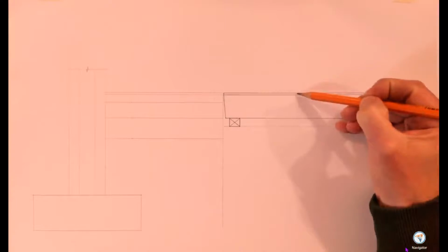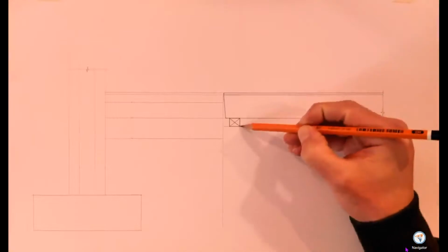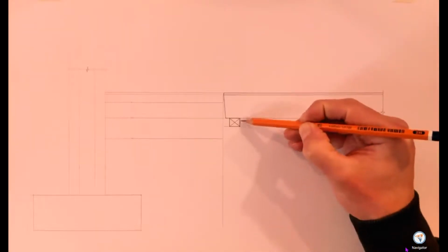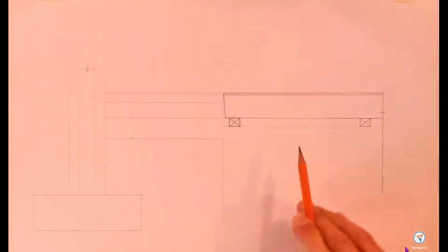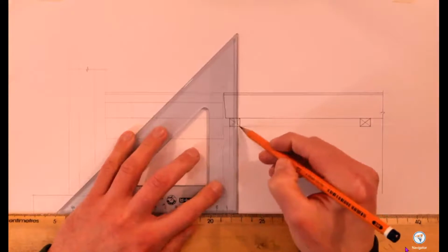I've drawn in the 20mm floor, 225 floor joists, and then our wall plate, 75 high by 100mm wide. There are two of them put in. That allows me to drop in the rising walls. So the rising walls are just set in here.